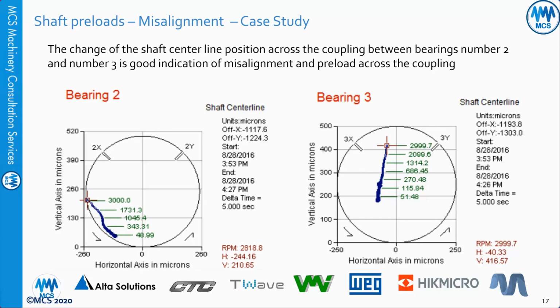All right, sticking on this screen, the same person was asking, can you have a preload in case of unbalance? They are seeing the preload on the 1x filtered vibration. Like, if you have unbalance, can you have preload? Well, I didn't get the question that much. Let me go back to their original one here. Is the uncentered time waveform a form of preload?